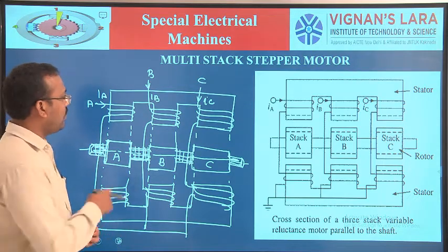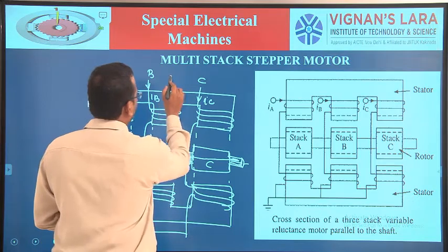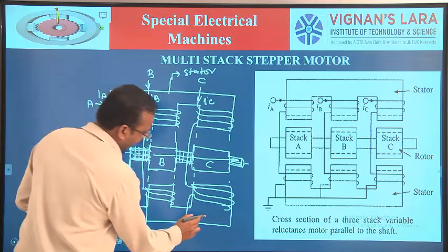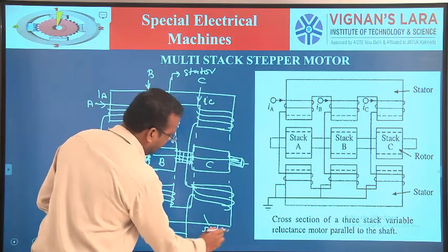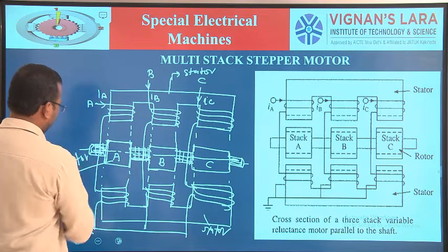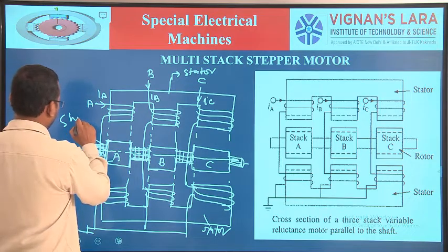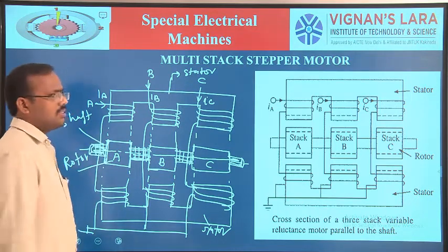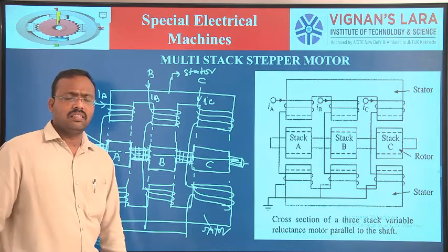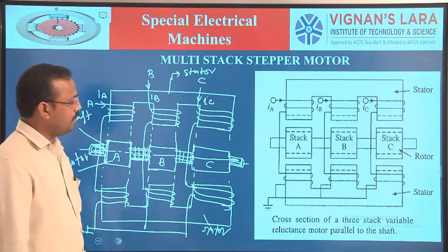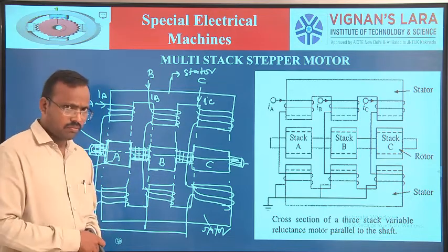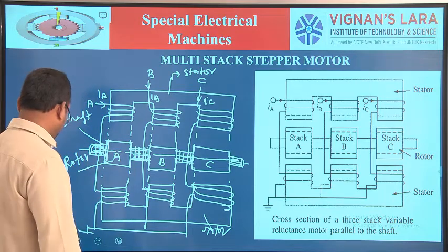See here, this is a stator. This is another phase of stator. This is your rotor. So the rotor does not carry any windings. It is made up of silicon steel laminations. So this is the complete construction of the multi-stack stepper motor. We'll see what is next.